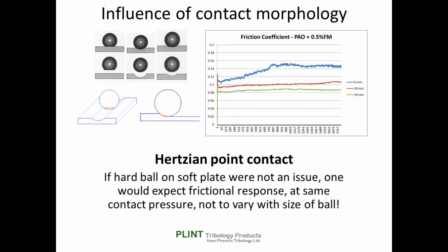In this case, we would expect an elliptical contact patch. However, with reciprocating motion, at stroke end, we would expect the ball to conform to the formed end of the wear track, increasing the dimensions of the contact patch in the direction of motion.